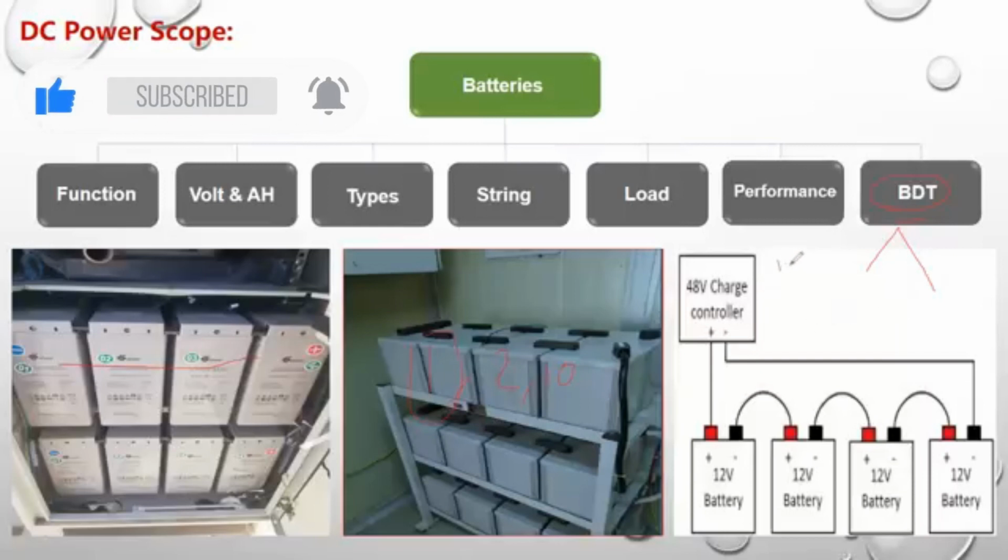So, for example, after half an hour, I see what the battery measurements are. And let's say after 60 minutes, I see what the battery measurements are as well. And after 120 minutes is the same. So intervals of half an hour each. And I start to see if the batteries discharge properly and logically, or if there is a battery that is not discharging well.